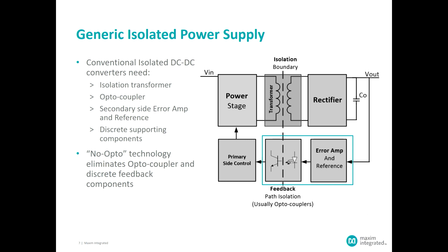Now typically that's just a signal level, and it's usually done with just an optocoupler, but there is some involvement there with that optocoupler that can get to be a problem and is worth finding some improvements over that. But essentially, the feedback signal also has to be isolated, and this block diagram shows it in this case with an optocoupler providing that isolation.